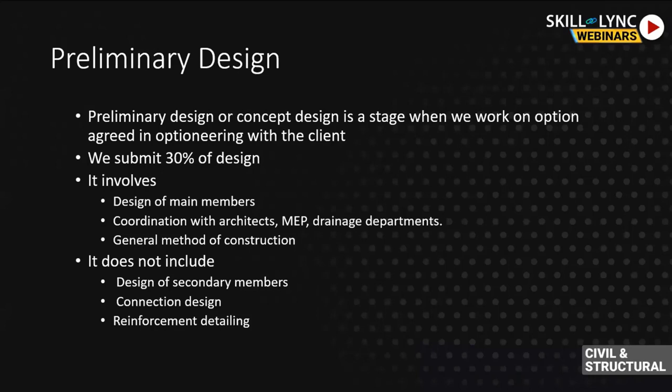Another thing that it does not include is the connection design, the weld or the bolt design, and also not the reinforcement detailing if you are going with RC for foundation. This is specifically for a steel building; the reinforcement detailing is not involved. For a concrete structure, reinforcement detailing is involved, but it's not a detailed reinforcement drawing that they are expecting from you.